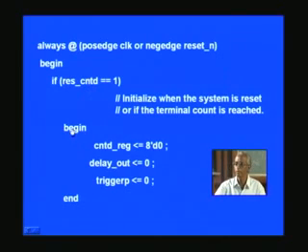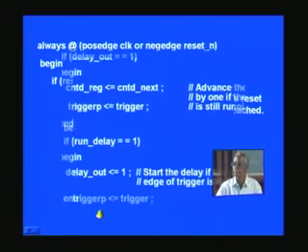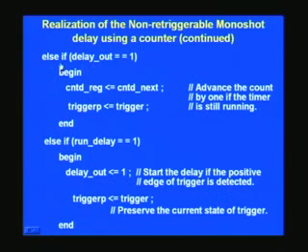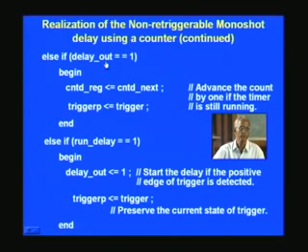And this being a block, we have a begin and end. Now we have another else if statement. First we sense the output: if it is 1, right? Delay is not at 1 yet, it will be 1 later on, but anyway we put this as the priority condition. If this happens, we need to increment the counter, because once the output has become 1, it means the counter has started running. So long as it is running, we can keep on incrementing the counter.